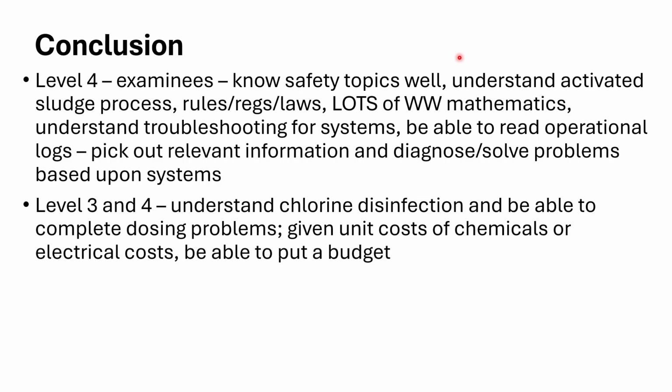The level 4, and maybe it was because I started working a lot more with level 4 stuff at the time, but still, you've got to know safety topics for every exam. You definitely have to understand the activated sludge process and the rules, regulations. A lot of math again, a lot of troubleshooting. Here's another thing that gets added on. You've got to be able to read operational logs and pick out what's relevant. They're going to give you a paragraph, a bunch of data, and then ask you 3 or 4 questions on that data. You've got to know what to pick out from the log they give you and explain it or troubleshoot it.